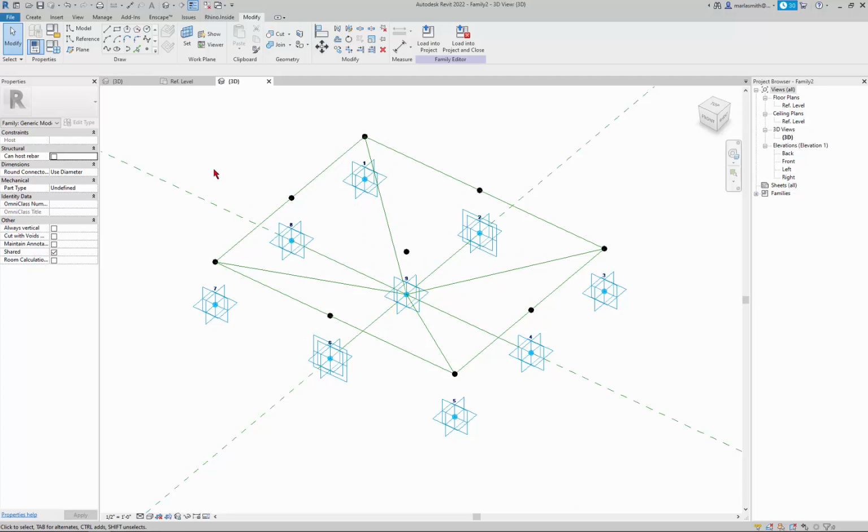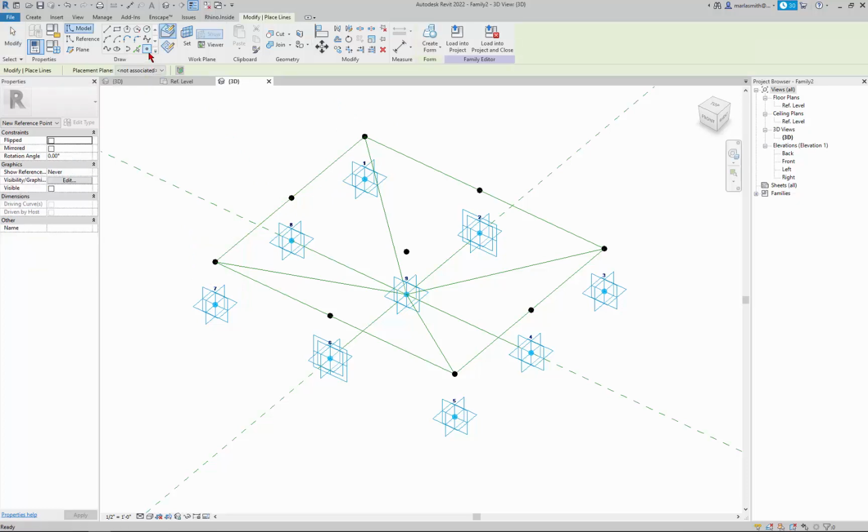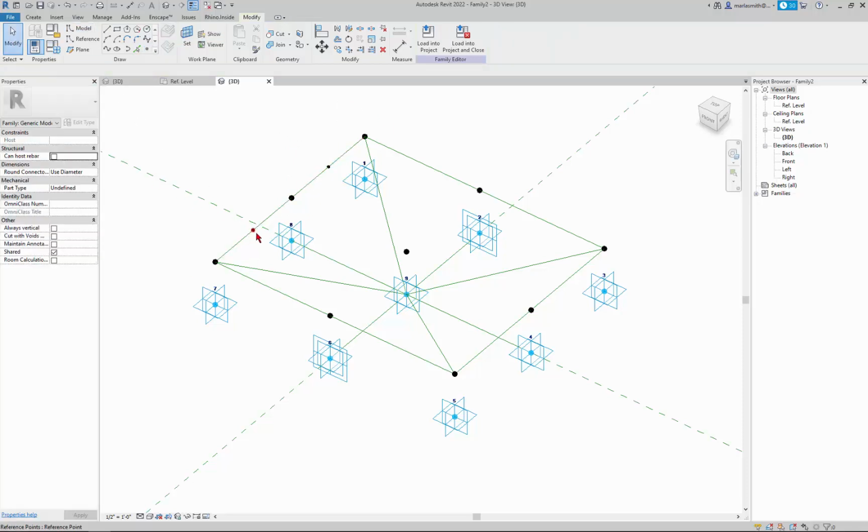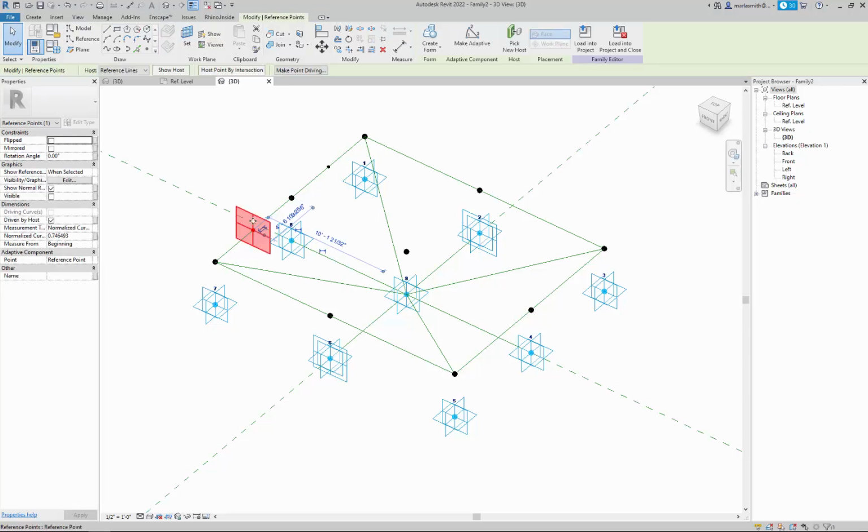So for later, if I'm hosting points, then 0 and 1 will be the same ends. And then the next thing I'm going to do is put a blended sweep on these guys. On these top ones, because they're single lines, we're going to have to put two circles and do a blended sweep. And you do that by placing points. So I'm going to go to point and draw on face, and you host them on that line, right? So if I click on those, you see that these get small and they're actually hosted. You can't move them off of there.